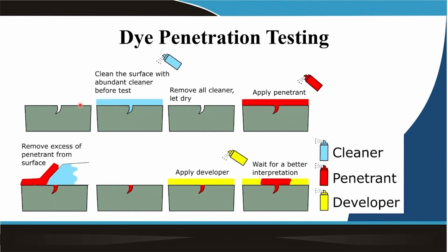So, you can remove those oxide layers in different ways as required for the specific oxide scale. After the surface is clean, you have to go on rinsing the surface. You can rinse it in water or alcohol, and then you have to apply the penetrant.